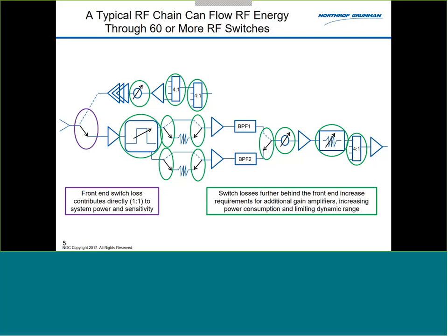right? So they don't have to be, but ideally, yes. Particularly as you go to higher frequencies. As you go to higher frequencies, when you start to try to combine different substrates, different chips, the parasitics that are involved with combining those become very important, particularly your parasitic inductances. So ideally, what you want is this entire process to be on a single MMIC, and that really helps to eliminate a lot of those problems. As you go down in frequency, that's less of a problem. But as you go down in frequency, it's easier to get a good switch performance. So once again, it's not as important.